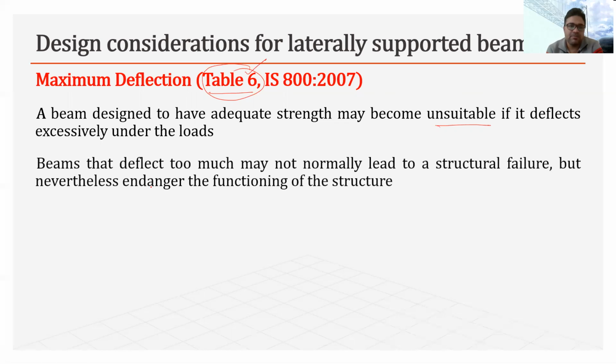As I said, beams that deflect too much may not normally lead to structural failure, but nevertheless endanger the functioning of the structure. A beam may take the required load, but if it is deflecting more, it may endanger the functioning of the structure.